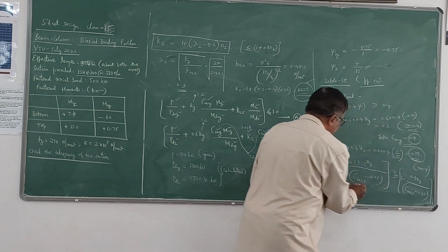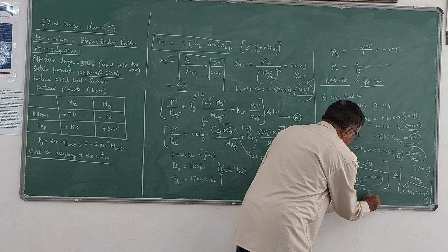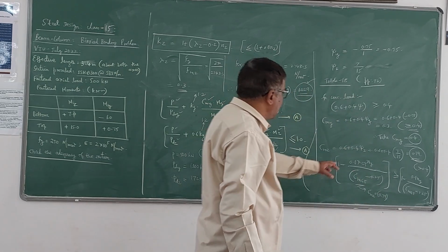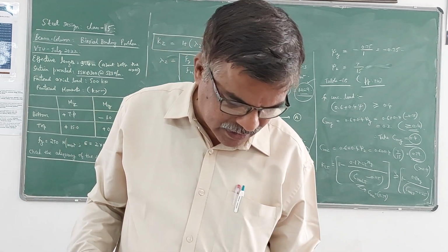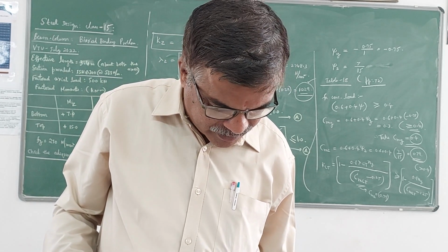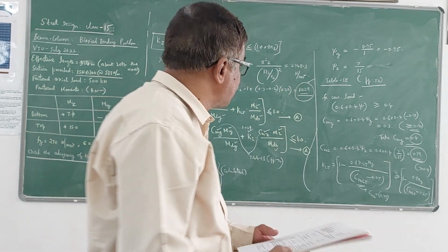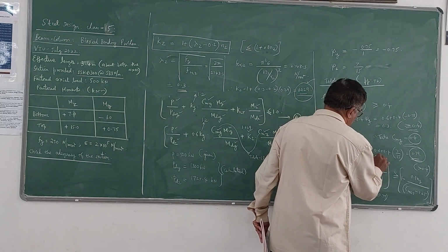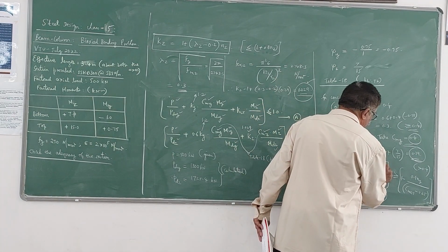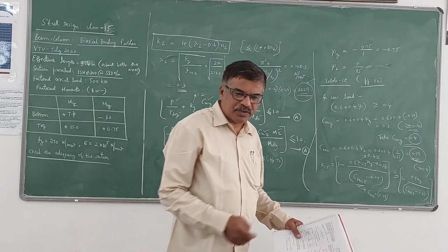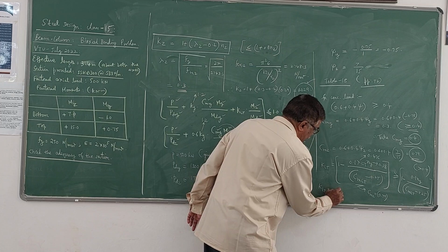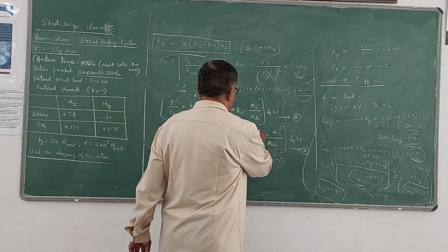Here CMLT can normally be taken as equal to CMZ. That is the higher value which you can take, 0.79. So CMLT can be taken as 0.79. Lambda LT value we have already got as 0.476. Then the NY value, of course, we found in the last step. I think it is 0.38, and this value is 0.79. If you substitute all these values and simplify, you will get KLT as 0.967. Now this KLT value is also obtained.